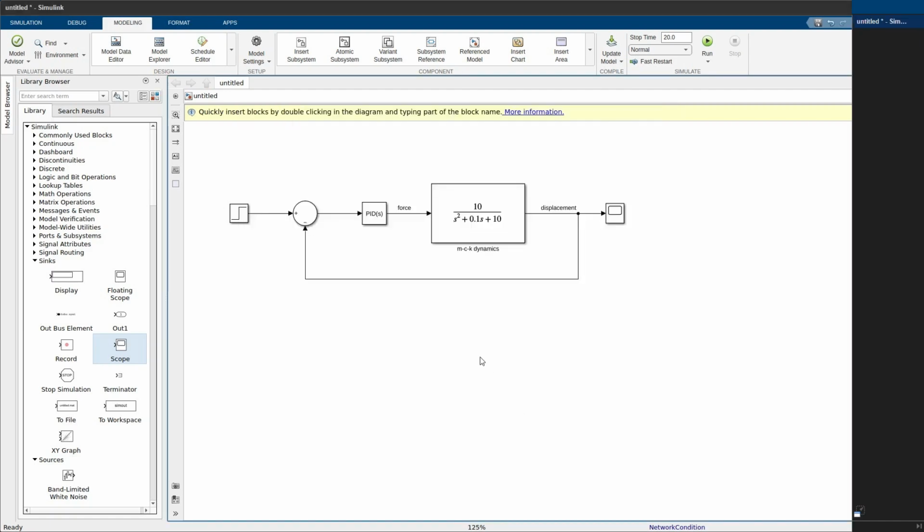All right, so now let's get to the PID gains. Here, I'm assuming that you already designed your PID gains based on some criteria you have for a displacement profile. For example, you may have a settling time requirement, or some maximum overshoot you can allow, maybe 5%, 2%, who knows. Then you developed the closed system transfer function and did what we call a pole placement procedure to find a candidate set of PID gains. Now you want to refine those, and maybe search for better gains, by which I mean a set of gains that will give you a more desirable displacement dynamics.